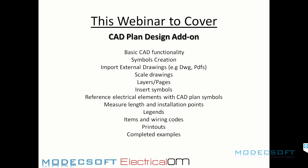We can then scale those, add them into different layers, produce different layer floors and layouts for your designs, and then use that to drop into our locations, things like socket outlets and light fittings. We can reference those elements and match them in to our core software where we're doing our schematic design. So where we've created socket circuits or lighting circuits, we can match them into the design. It will take things like lengths, number of points that we've put in the drawings, and it will take this data as we're doing our CADing and put all this information into our design calculations and schematic.